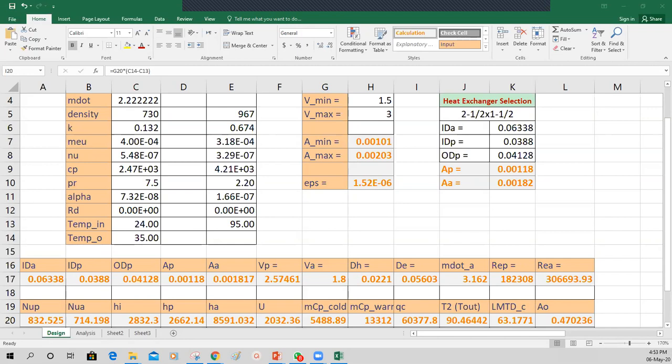The formula is given in my slide, and in the textbook also, the log mean temperature difference for parallel flow and counterflow. It is given on page 407, equation 8.9. It's for counterflow. So you can take from there the log mean temperature difference, 8.10, delta T for counterflow.